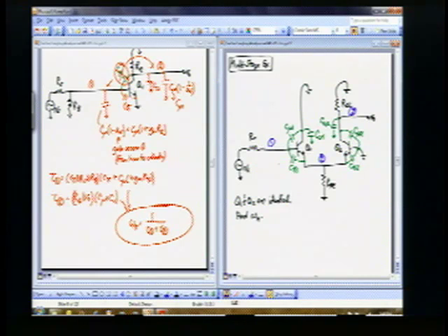Well, first of all, I can do some simplifications out of this whole thing. And what are some of the simplifications I have? Well, first of all, I look at this CCS1. In the small signal circuit for this emitter coupled pair, you had the bias thing earlier on. I showed that in the previous lecture. But in this small signal circuit, this is grounded here. And so you've got ground at both ends of CCS1. That means it's simply not there. We're just going to neglect it because it's got both ends grounded. It can't do anything in this circuit.